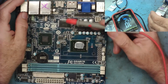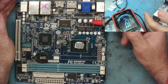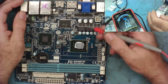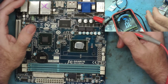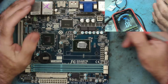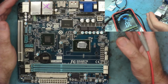Well, actually no, it doesn't really mean that, because we know that the conduction of the MOSFET is controlled by the gate voltage, positive or negative with respect to the source. If we know we have a MOSFET and we measure the voltage on the source and the drain, especially the voltage difference between the source and drain, then we can quickly realise whether the MOSFET should be switched on or off. And if it's switched on, then the drain and source should be basically the same voltage. So I would suggest the best way to test MOSFETs in circuit is using your multimeter in volts mode with the device powered up.